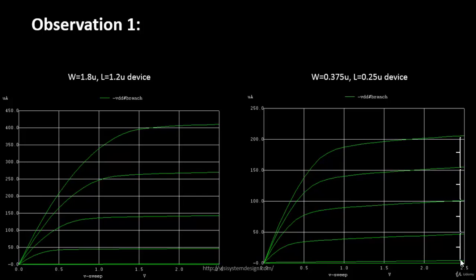At a gate voltage of 1 volt, you have a drain current of let's say 40 microamps, and so on. So in this area things are still quadratic, but as you move from this point till this point, things are linear. Your drain current at every point after that is linearly increasing with your gate voltage.